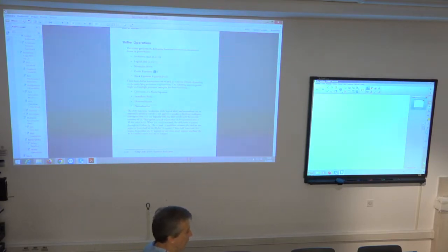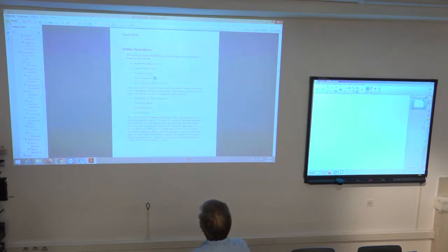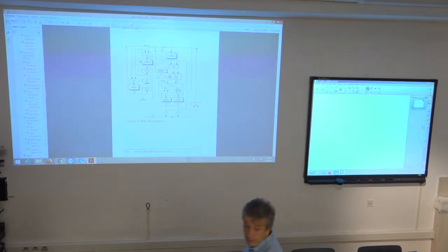It doesn't matter whether it's arithmetic or logical if it is left shift. Okay, it performs the left shift with a negated value of the SE register. So that is the reason why in this architecture you have this negate. This negate is activated only for the normalization instruction. For a normal shift instruction, you simply pass this SE register directly as a control input to the shifter array.